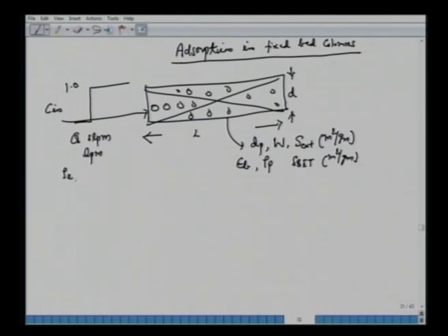We know the densities rho L and rho G. So we bring in contact here, and we are interested in monitoring this concentration profile, C with time, how the profile at the outlet changes. Of course, if you recall in our lectures, we call this a breakthrough curve, and we had a very rigorous set of equations.